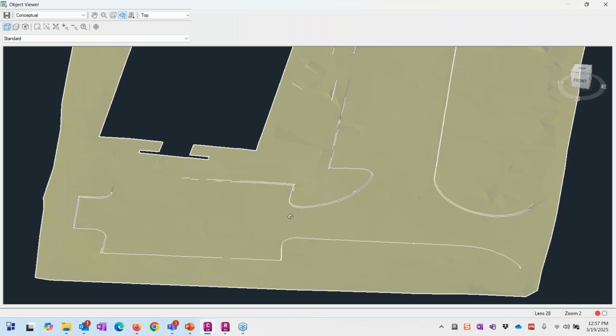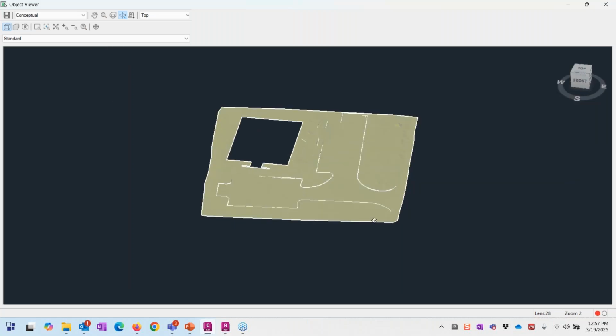Would I do ADA and ramp design with this? No. I'm still going to need traditional survey. But if I'm doing this over a 10, 50, 20, 100 acre site with some drainage swales for a subdivision design or preliminary design or drainage all day long, it's accurate enough.